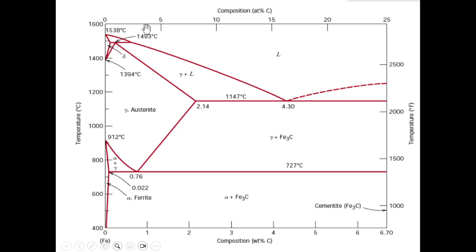So sometimes the phase diagram is so small that they don't really put in the symbol to tell you what are the phases that are present, right? If that is the case, you can fill in the blank yourself, right? For example, in this phase area here, this little triangle here, there's no symbol saying what phase is there, right?